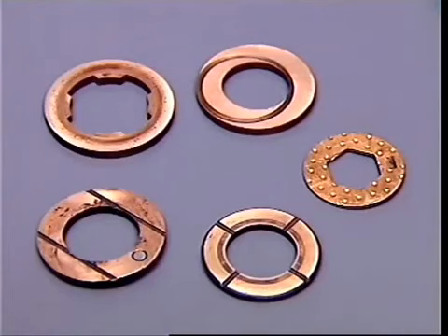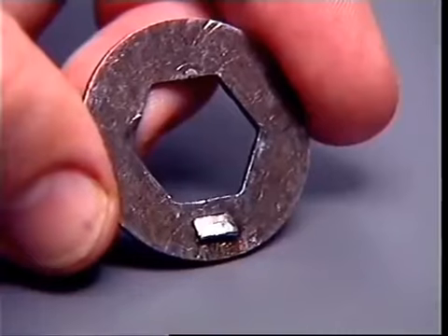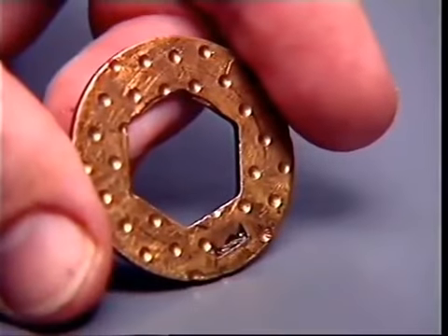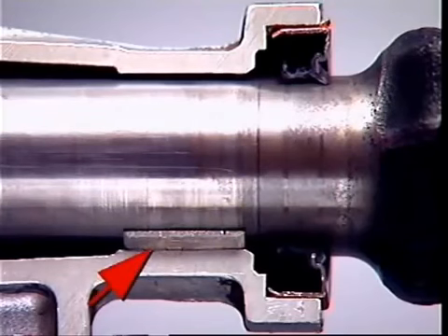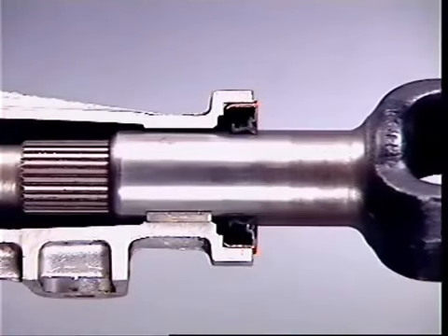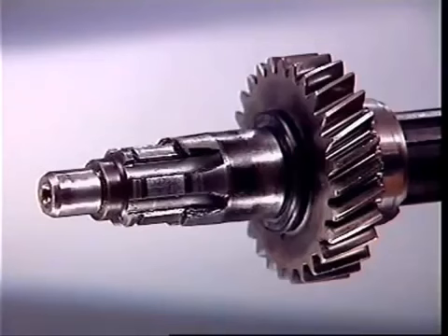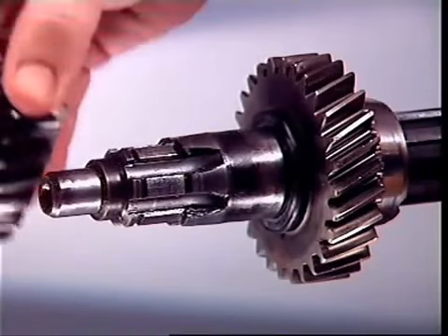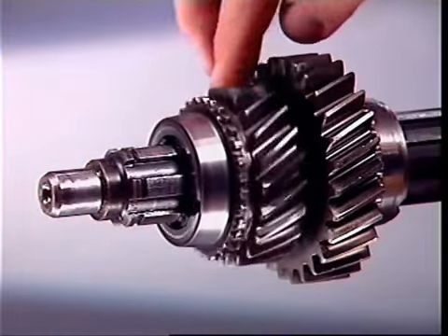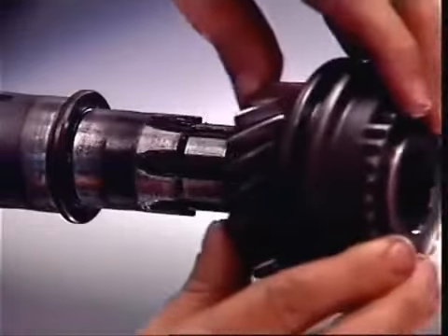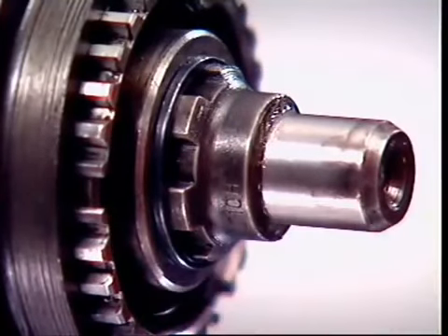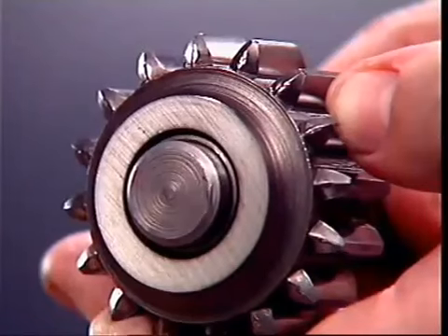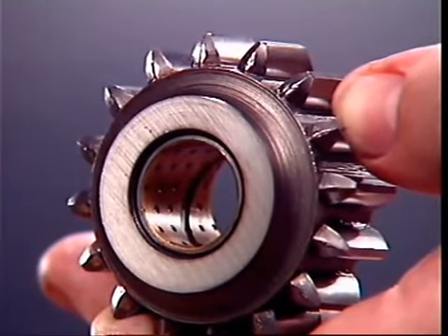Thrust washers are plain bearings. They are usually bronze, but can be steel, with the bronze facing on one side. They can be dimpled or grooved to allow for lubrication. A plain bearing can also be used in the extension housing to support the front of the propeller shaft. Machined and hardened surfaces on the main shaft can provide bearings for the freely rotating gears. Flanges and snap rings on the main shaft locate the gears and cater for end thrust. A plain bearing is also used for the reverse idler.